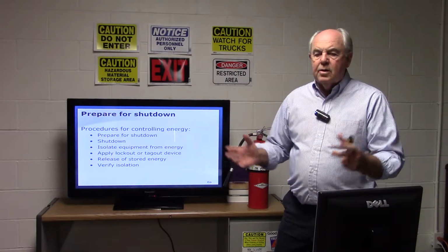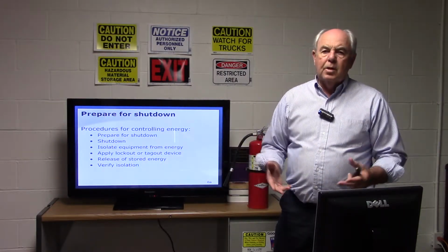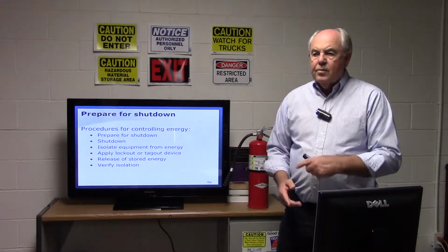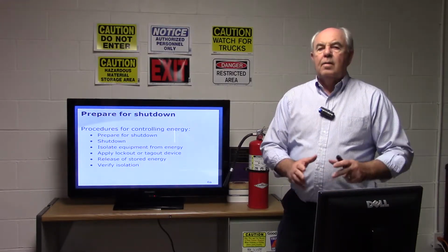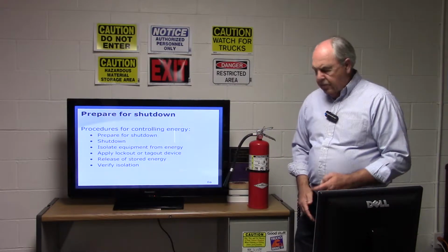Look at all the things that are coming in. Hydraulic, electrical, pneumatic, whatever it might be. It could be multiple sources. So you want to go back through those. But if that machine doesn't move, then you're ready to move into either the repair or the maintenance or whatever it is you're there for.